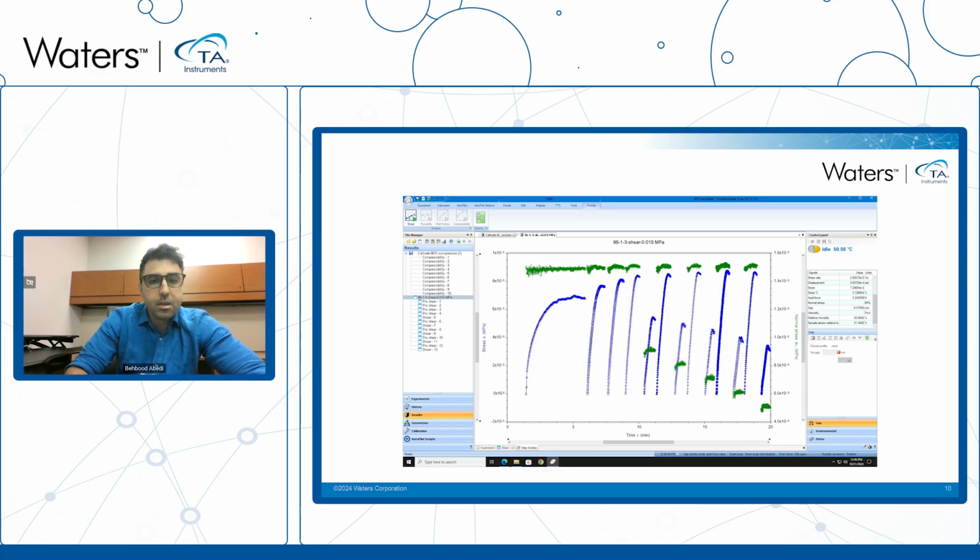So you have here 5 consolidation stress values, which are the same value. You can get the average of the 5 shear stress values. So you would have 5 yield stress points at reducing normal stress, plus 1 average shear stress at consolidation stress. So 5 plus 1. And again, easily, you see here at the top left, you can just click on shear and TRIOS does all the analysis for you. I will show you how this turned out.